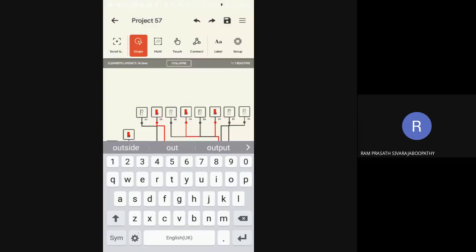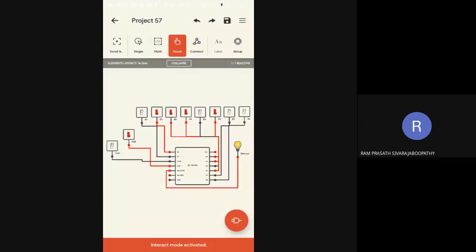Like that I name. Clear? Suppose I change the data randomly. Now count. How many number of ones are there? 6 number of ones. So it is already even parity. So what should the parity bit be? Now it is 0. So, did you understand the parity generator? Is it clear for everyone?